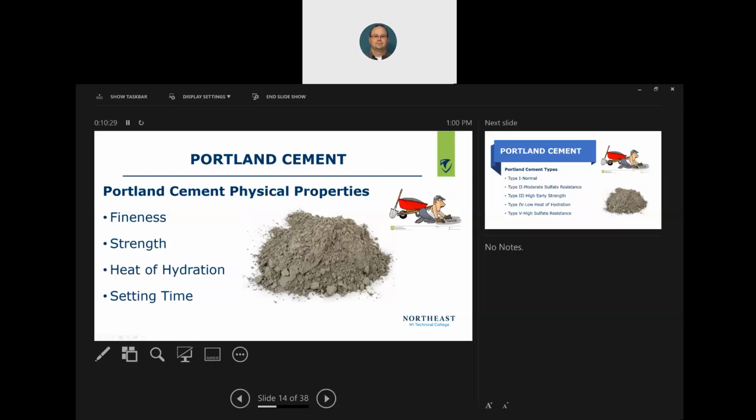So this is why they add the gypsum. They have to add gypsum to slow down the setting time. Otherwise, literally, there will be no time for it to go from the concrete truck to the site, because it'll set already. So they need to slow that down.